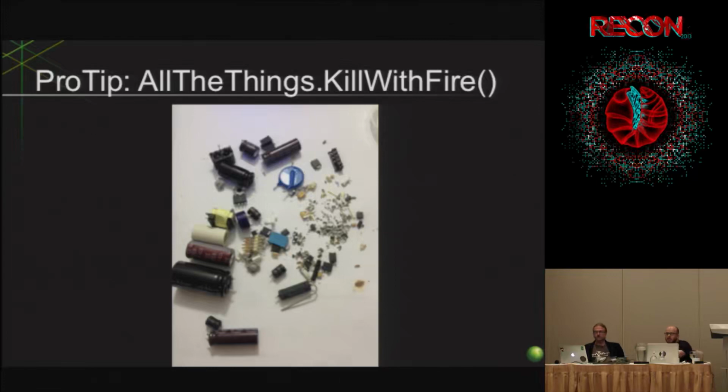On these, the boards are still relatively simple. They're multi-layer, but usually your internal layers are just ground planes or power or something, so they're really not very complex. That makes it simple to start tracing out and figuring out what's talking to what. Because a lot of times later, when we talk about how to enable debug or do something like that, typically we're raising or lowering a pin or two. So it's nice to get a good view into that board without just staring and staring at it, to get that quick reference of, okay, I need to solder here, or cut this trace, or whatever.